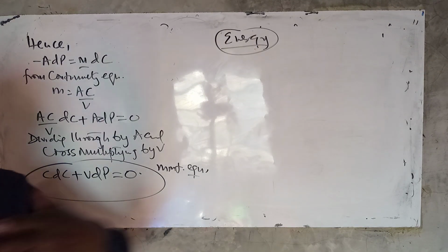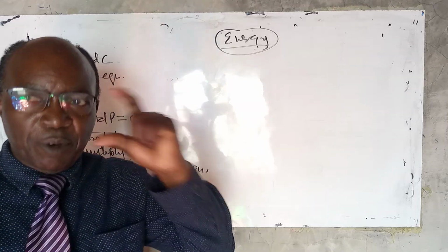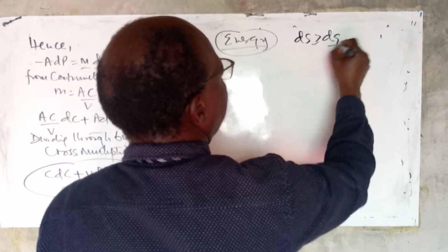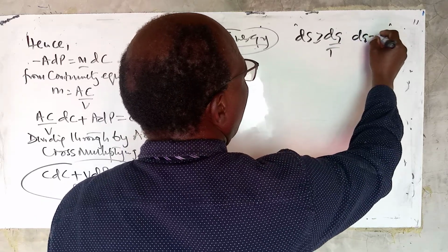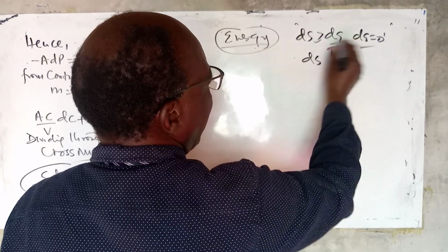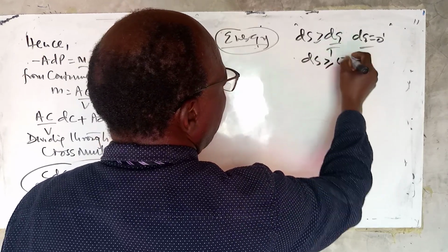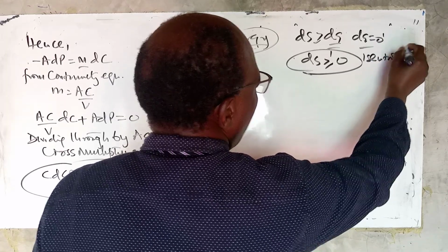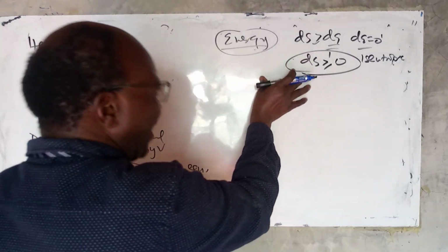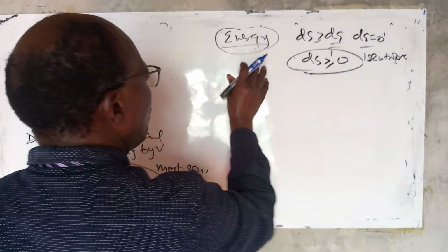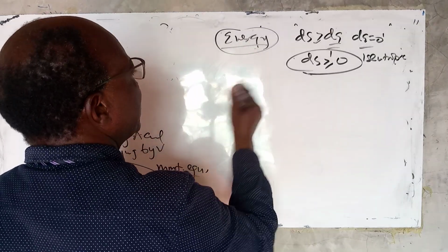And don't forget isentropic flow, because we said from Clausius inequality, ds was greater or equal to dq over T. So that when dq was equal to 0, that's adiabatic, then ds greater or equal to 0, that is isentropic. And so when we worked with that, from first principle,